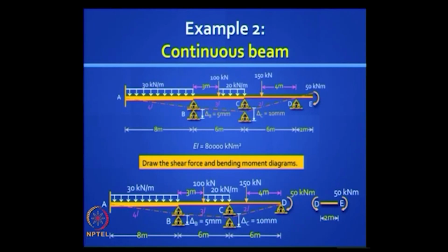So you are now applying this as a nodal moment, except that it is not really going to a global coordinate. We will explain that shortly. Okay, now tell me, we've got a reduced problem now, just a 3 span continuous beam. What is the degree of kinematic indeterminacy in this? It's just 2 if you want to take advantage of the hinge at D, right. So from 5 it's a massive plunge to 2. So that's a clever thing, and we should do it correctly without making any mistakes. So please pay attention. By the way, we did this in slope deflection method, we did this in moment distribution method, we will now do it in matrix method.